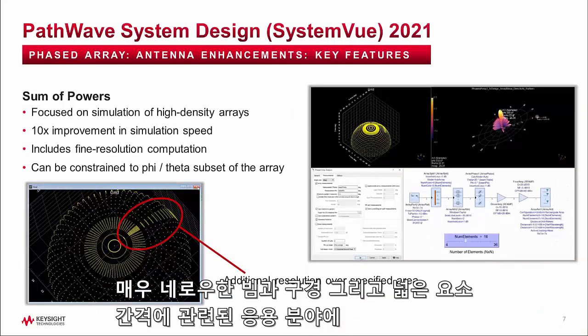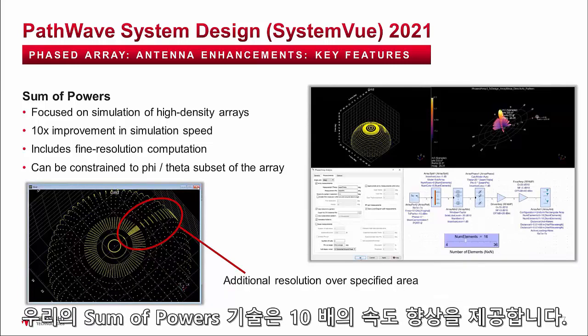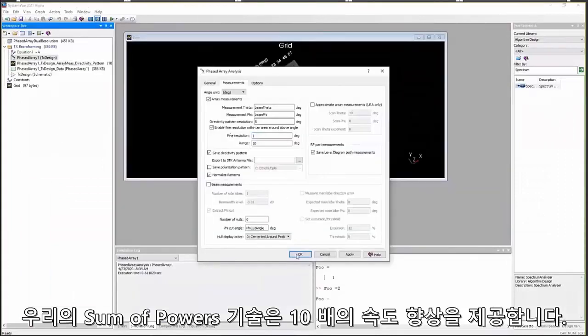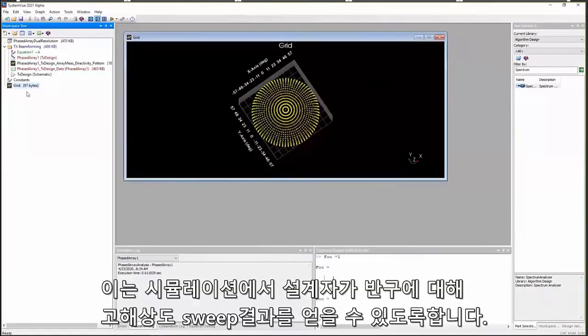For applications involving very narrow beam apertures and larger element spacing, our sum of powers technique offers a ×10 speed up in swept simulations whilst allowing designers to get high resolution sweeps over a portion of the hemisphere.